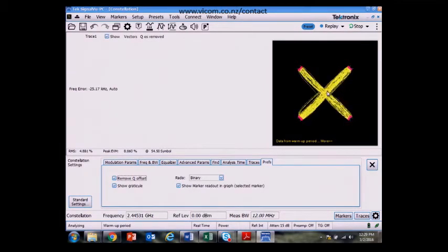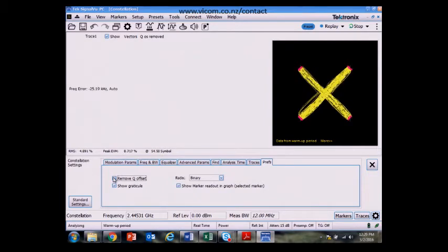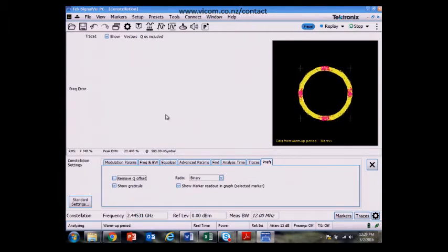but now it shows a lot of zero crossings. One of the advantages of using a ZigBee device is that physically, in reality, I don't have the zero crossings, but it makes it difficult to display this abstract implementation of ZigBee signals in the constellation diagram. So you can look at this either way, either with the constellation diagram showing up at the expected points or without the Q offset removed, that shows physically how the signal is really being transmitted, avoiding the zero crossings.